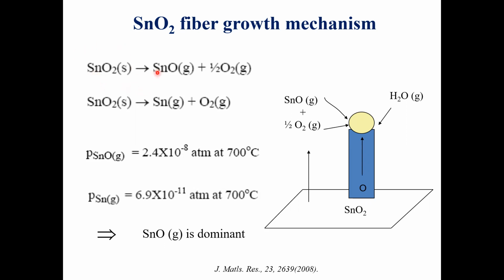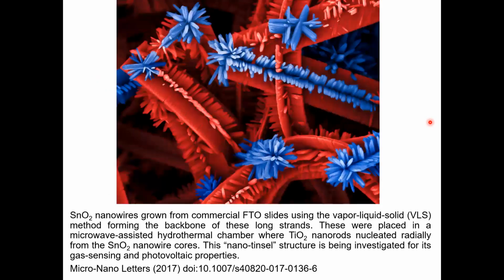So to keep the tin dioxide in the oxide state, we have to introduce some humidity. So your hydrogen-nitrogen gas is bubbled through water, so it carries some water vapor that raises the PO2 above the oxidation boundary between tin and tin dioxide. So this is an interesting process.